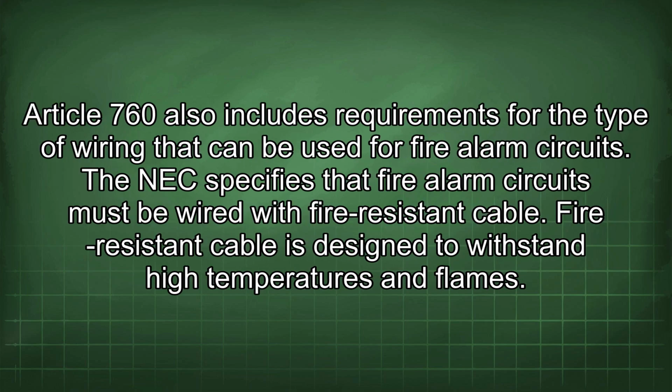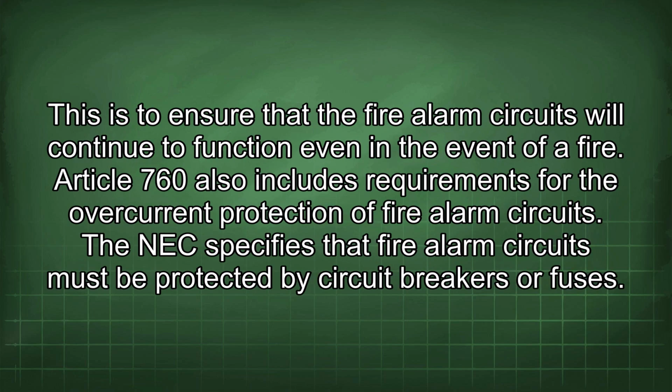Article 760 also includes requirements for the type of wiring that can be used for fire alarm circuits. The NEC specifies that fire alarm circuits must be wired with fire-resistant cable. Fire-resistant cable is designed to withstand high temperatures and flames. This is to ensure that the fire alarm circuits will continue to function even in the event of a fire.